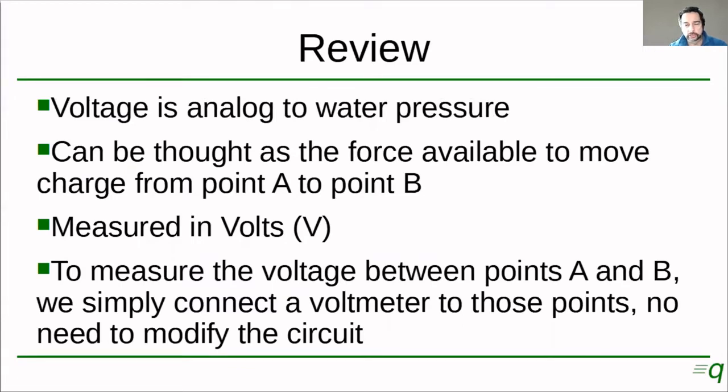We also studied voltage, right? Voltage is similar to water pressure, we said. And you can think of it as the available force to move charge from point A to point B. We measure voltage in volts, and to actually measure it in the circuit, we don't have to modify the circuit at all. We connect the voltmeter between the points A and B where we want to measure, and we just take the reading, and that's it.